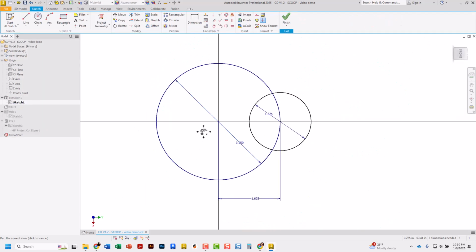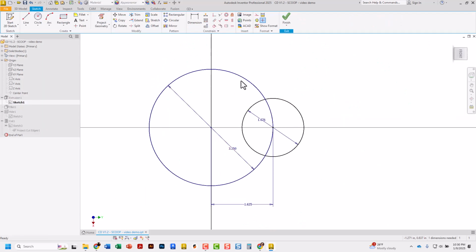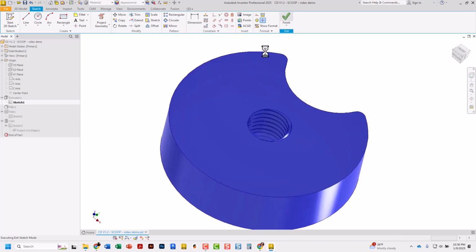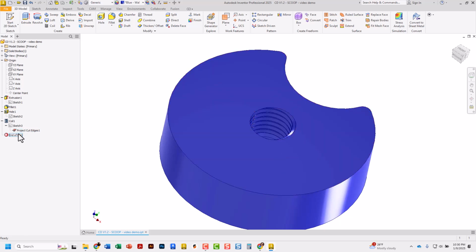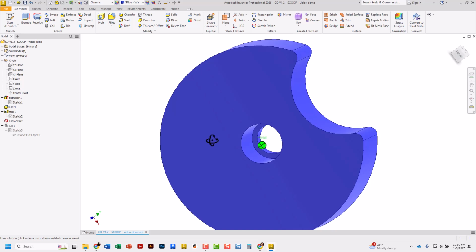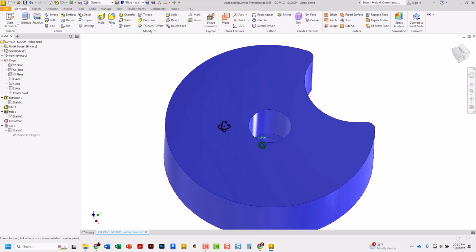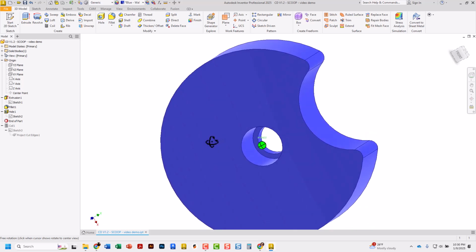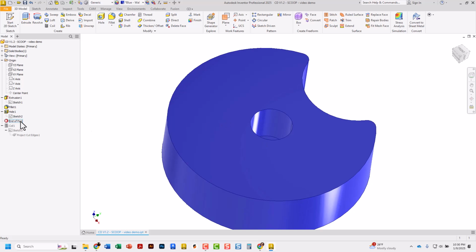So how we're going to do that is to make sure that our very first sketch when we started was on the origin point and that we have these grid lines or other work planes that will pass through that. We leave there and then you'll finish modeling out the hole as needed. Actually, I'll just show it like that. So we have that hole with a counter bore, a deep counter bore, smaller part at the end. And then we are going to model threads on that by sketching on a work plane